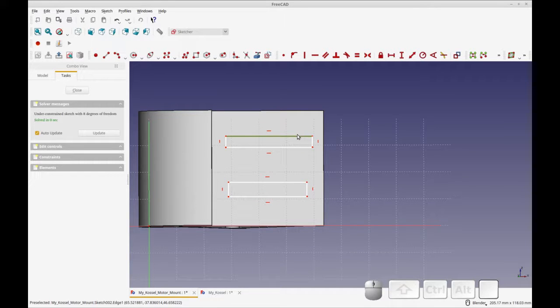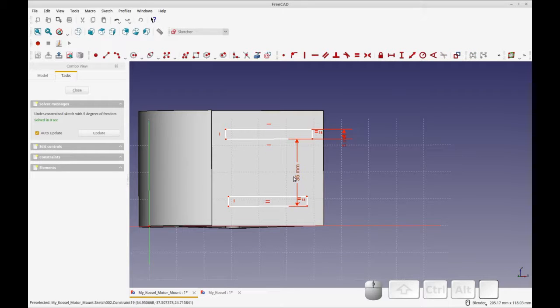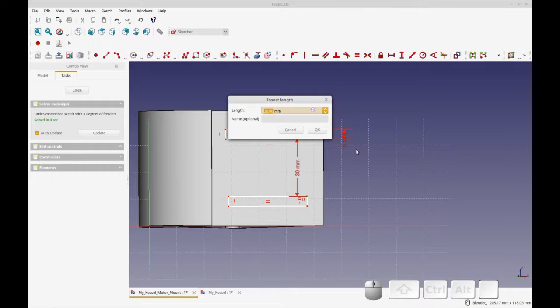And we're going to set the dimensions of the boxes. We're going to set the side dimensions, and it's going to be set to 5 millimeters. And then we're going to set equalities to here. We don't need to on the other side because we're going to be leaving these horizontal constraints, and we're going to set the distance between these to 35 millimeters, and that's incorrect. It should be between these, 35 millimeters.